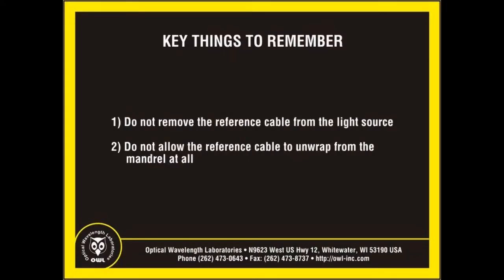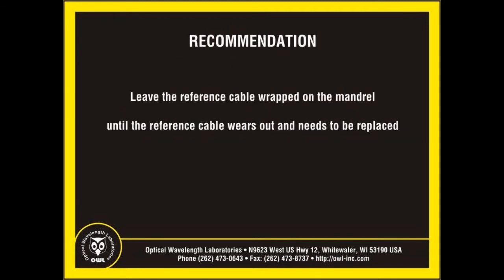The mandrel wrapped cable will be attached to the fiber optic light source during all phases of an insertion loss test, from setting an optical reference or zeroing all the way through until all the fibers have been tested. Two key things to remember once the optical reference has been set. First, do not remove the reference cable from the light source, and second, do not unwrap the reference cable from the mandrel. In fact, it is recommended to leave the reference cable wrapped around the mandrel until the reference cable itself needs to be replaced.